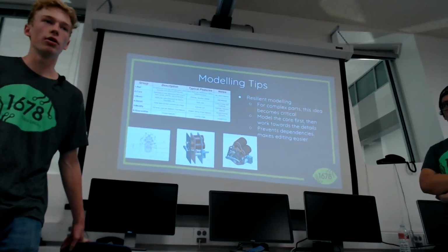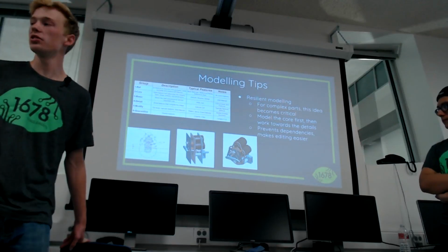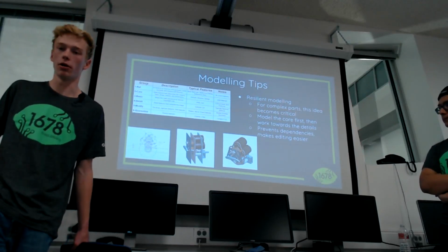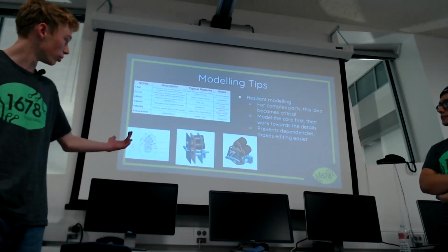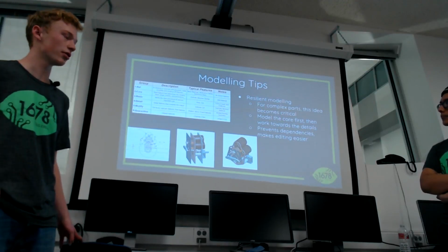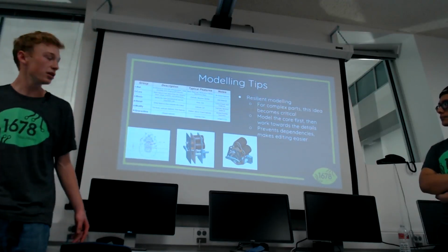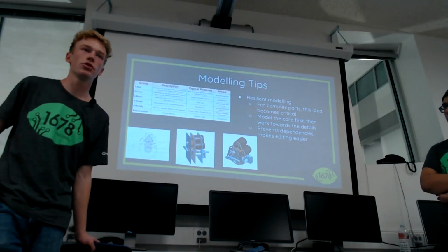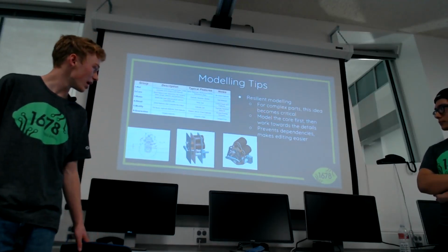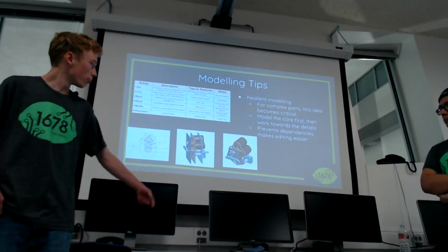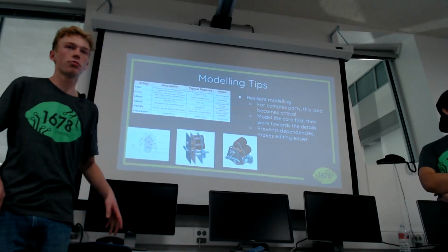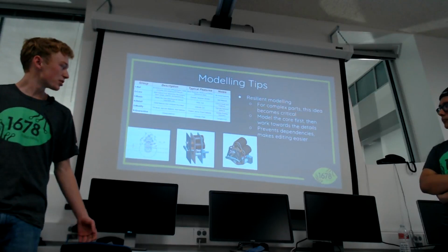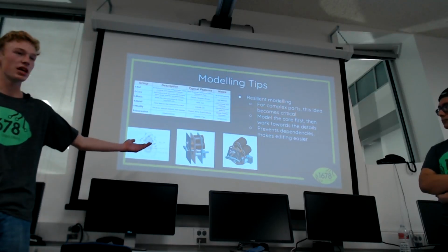And it's all about your time. If you're wasting time resiliently modeling, you're doing it wrong. As an example, I want to talk about these gearbox plates here because this illustrates how it can be done. The idea is you start with a master sketch of all the critical design features that you know where they are, and you can go back and edit them at any time. Then you make a really basic extrude, just the core features. You guys can see that's just a bunch of rectangles with holes cut out in them.